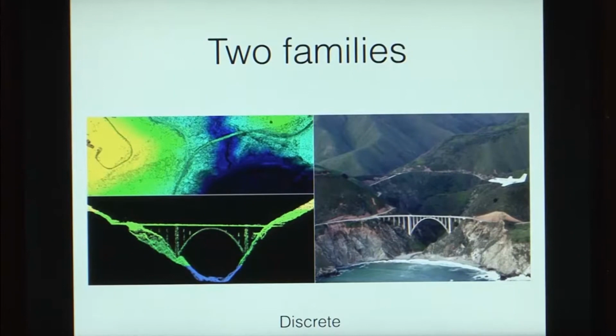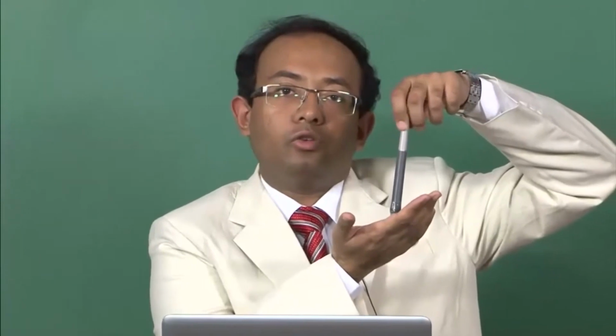Now, what sort of wavelengths do we use in lidar? Remember that it is a laser system and a laser beam has a fixed wavelength. So, what are the wavelengths that we use? There are a number of considerations here. One is that your beam should be able to interact with the object. So, essentially we use those wavelengths that can interact with the object. Two is the safety criterion. For instance, if you are putting a laser light on an aircraft and it is shooting down to the earth, and somebody is looking up at the sky, or intercepting that reflected laser beam, then his or her eyes should not get damaged. Those are the two considerations.